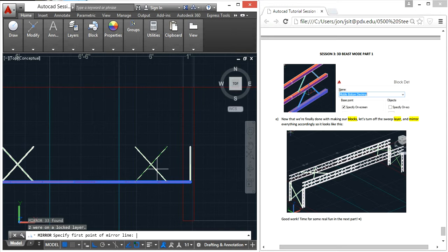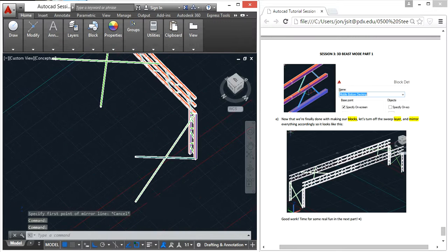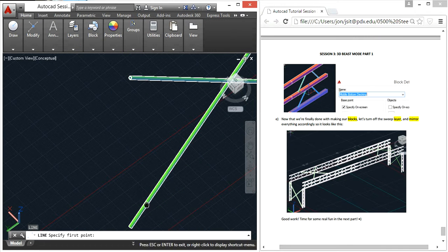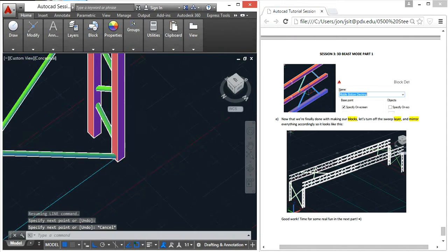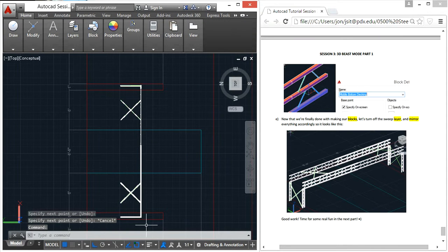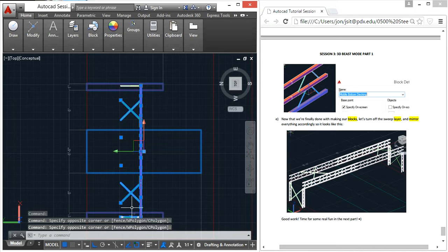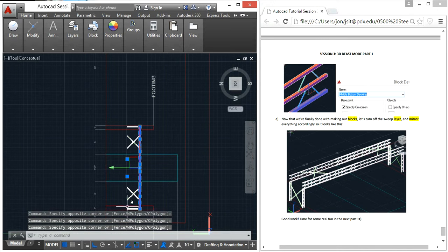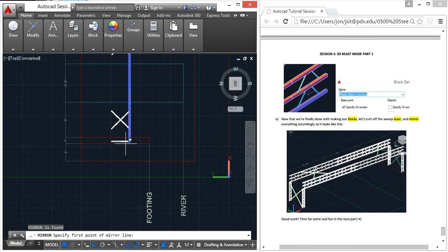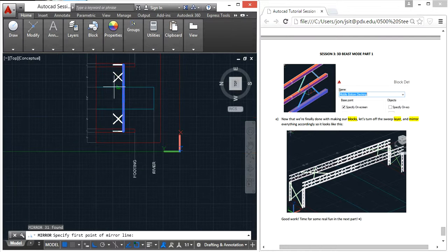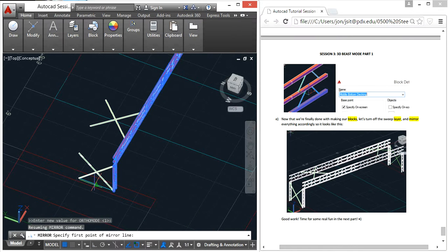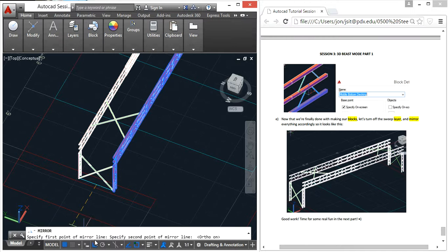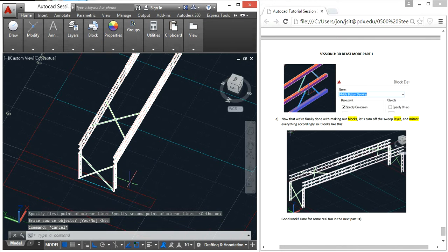Unfortunately though, if I try the mirror tool, I don't have a line to mirror about, so that's why we create lines. So I'm going to use this to measure a line, from here to the opposite side. There. Bang. Go back to top view. Select all of that. Basically, just hold shift, unselect all of that. And then MI, I think my line is here. Or maybe this. Let's see. Oh, there it is. There we go. Turn ortho on. Click, and there you have it.